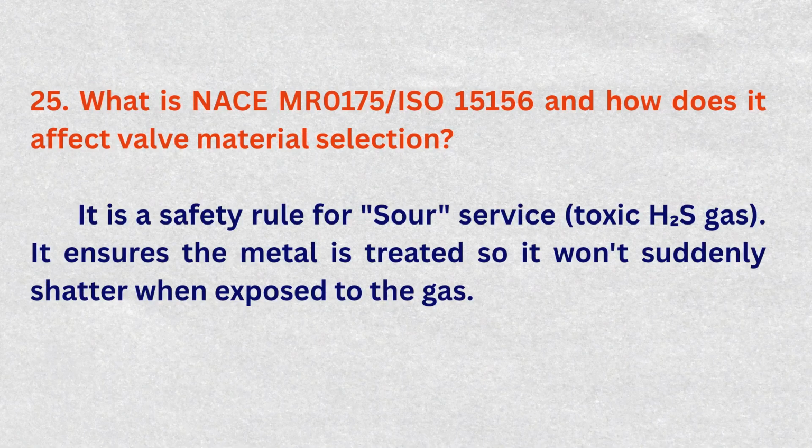What is NACE MR0175 ISO 15156 and how does it affect valve material selection? It is a safety rule for sour service, toxic H2S gas. It ensures the metal is treated so it won't suddenly shatter when exposed to the gas.